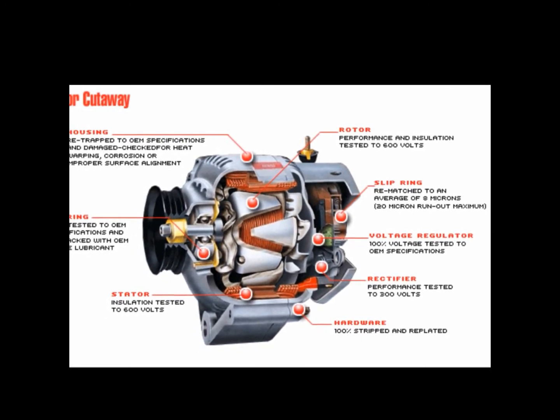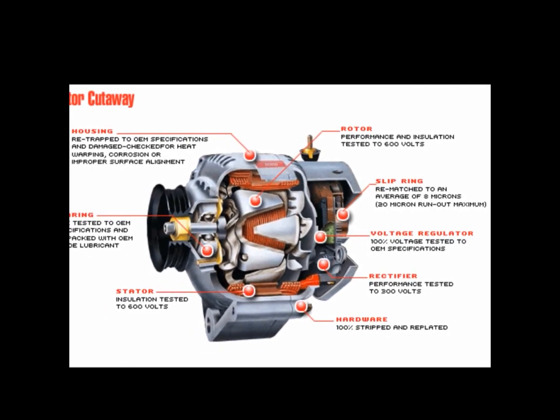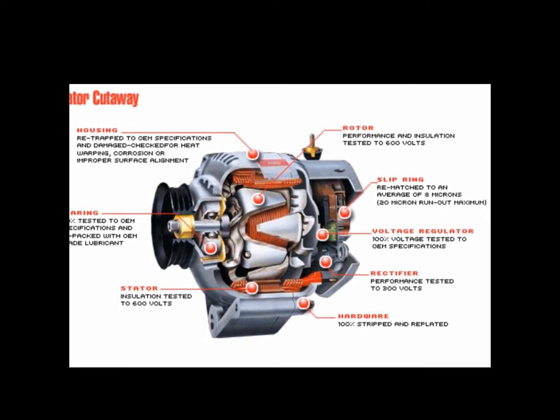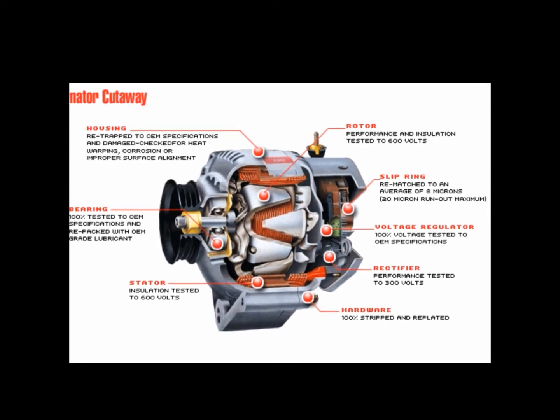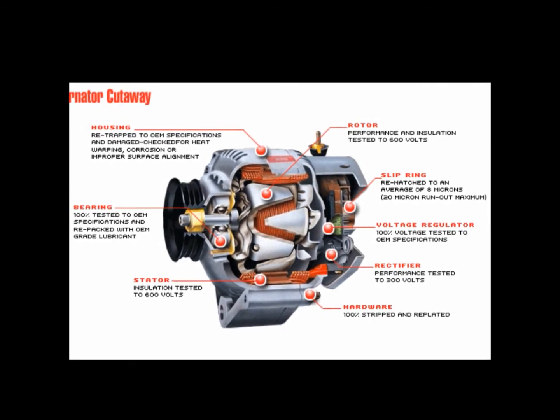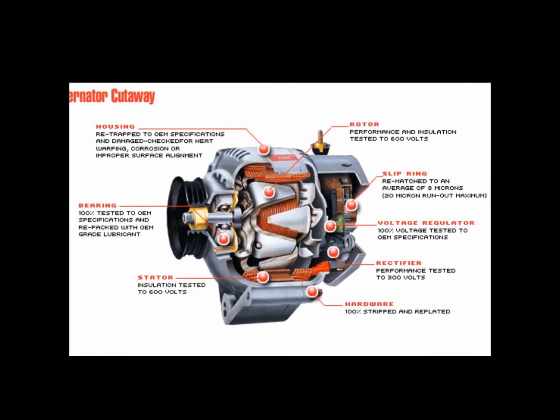The rectifier consists of diodes arranged to form a bridge network acting as a one-way valve so that the current generated in any winding will pass to the B+ terminal. The surge protection diode. This avalanche diode conducts when a surge voltage exceeds a given value.